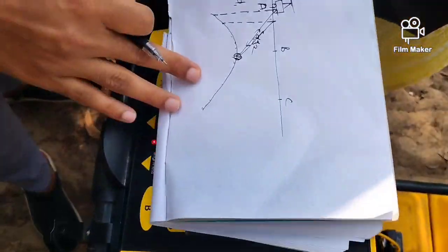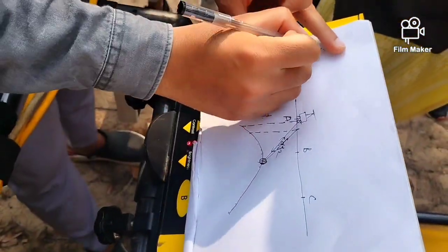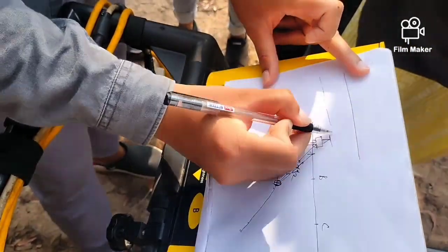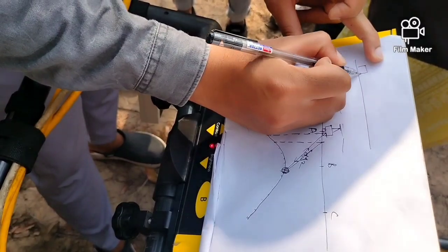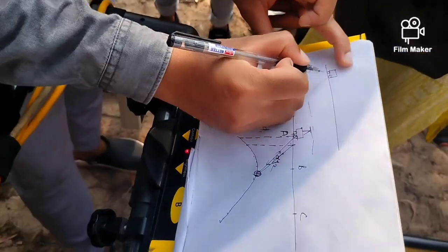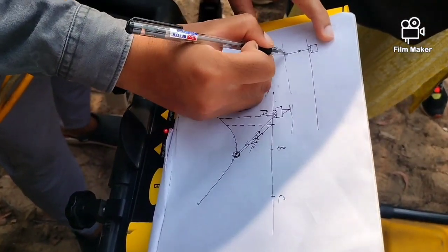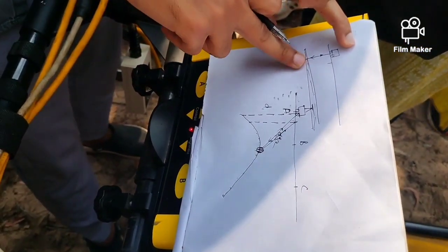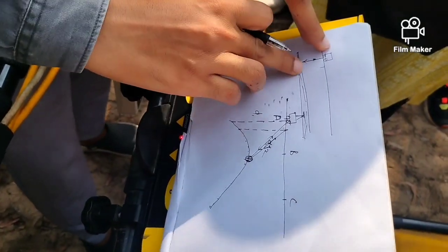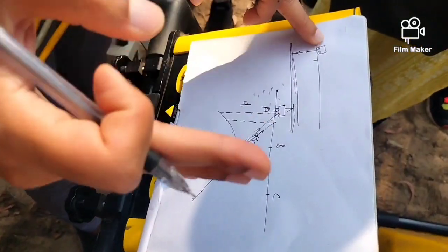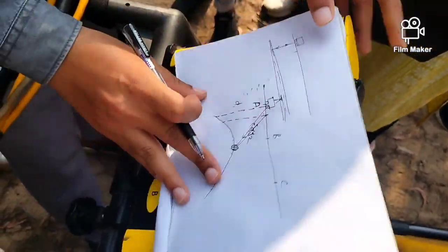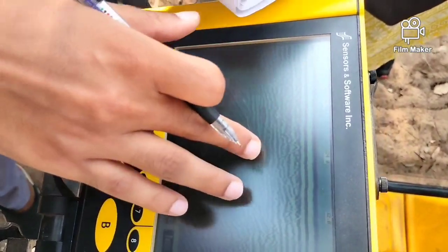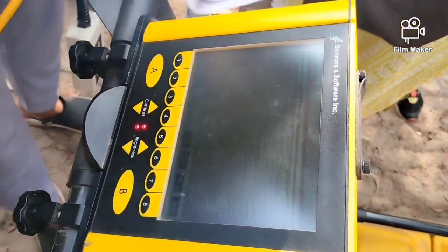If you would go on a planar surface, like let's say this is the subsurface, this is the surface, this is some layer in there. In this case, if GPR would go, it'll just trigger down and then come back, right? So you would see the same surface. There won't be any difference because the subsurface structure is at the same depth at all points. So these laminations that you see are the actual laminations. These hyperbolas you see are the point objects in there.